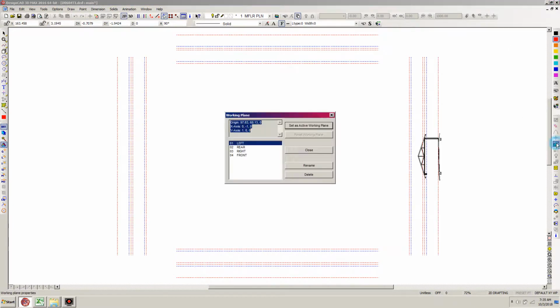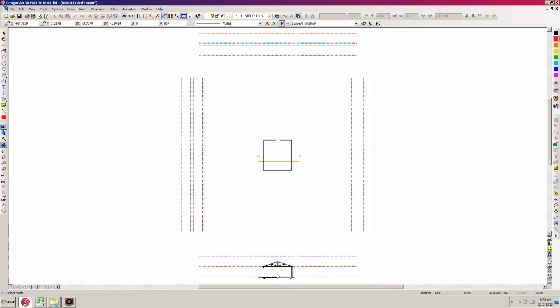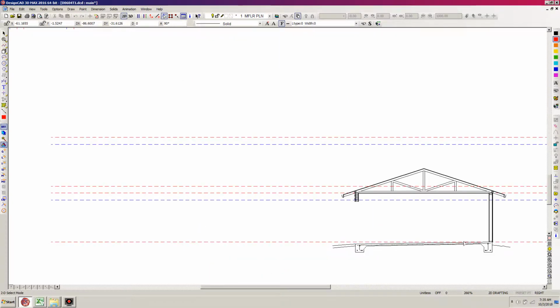So actually I'm going to roll this guy back around to the right and zoom up on this area here, and you can see the heights that we have. This is basically our main floor line right here, and that stair is going to have to drop down below that. So I'm assuming at this point that the lower landing for the stair is going to be roughly 1 foot below this finished floor line. It could even be a little bit lower than that, but if we need to, we can build up a little bit and have a step off of the landing.